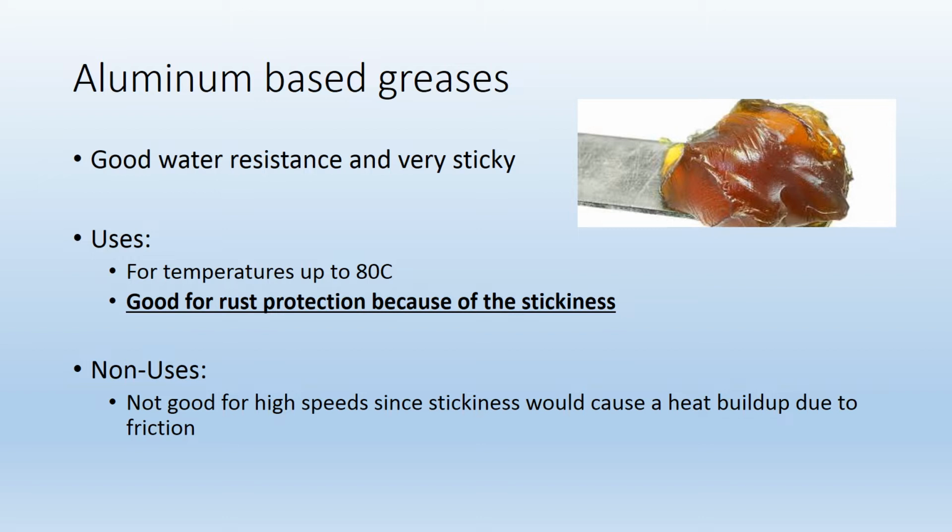Places where you do not want to be using aluminum-based greases are high-speed applications where that actual stickiness of the grease itself would actually generate a lot of heat.